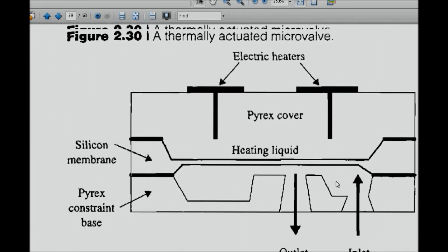You see here, this is again a thermally actuated type of valve, and this is a little bit simpler compared to the previous one. The cross section of this type of valve that you are seeing is sliced from one point. This design is going to control the flow rate from a normally open valve to a fully closed end. So normally it will be open, and whenever you want actuation, it is going to close.